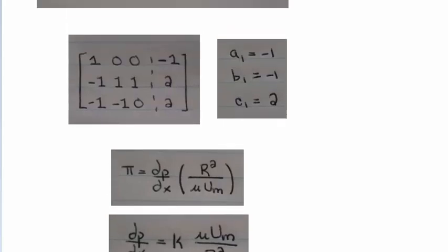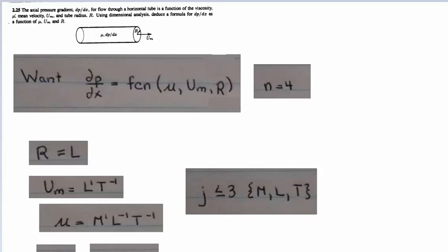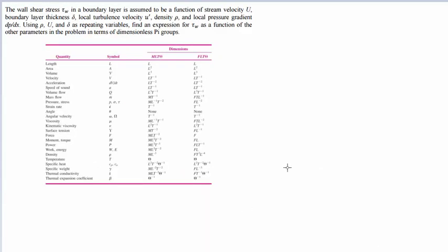Okay, so this is one of the simpler problems, so let's get into the nuances of the Buckingham pi theorem. So here we have yet another problem, and here our goal, once again, is always going to be, you have some variable, try to write it as a function of the other variables. And this chart's just here to help you out with the units, decomposing everything into M, L, T, and this theta over here. And theta is for temperature, it's not for degrees.